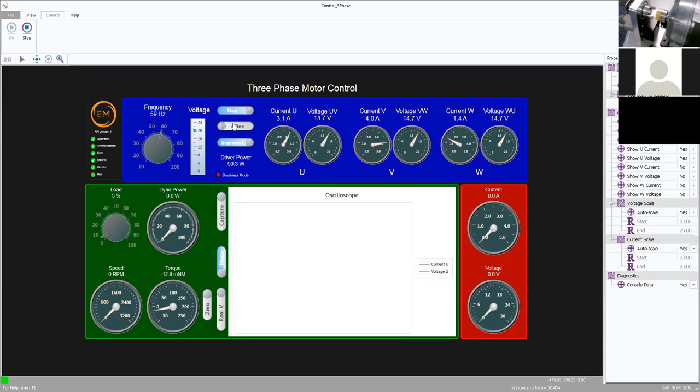There's a couple of switches here that universities will be interested in. We're using a bunch of very high power motor drivers to create the signals for the three-phase system. And basically, these outputs are able to go to 0 volts, to 24 volts, or to open circuit.